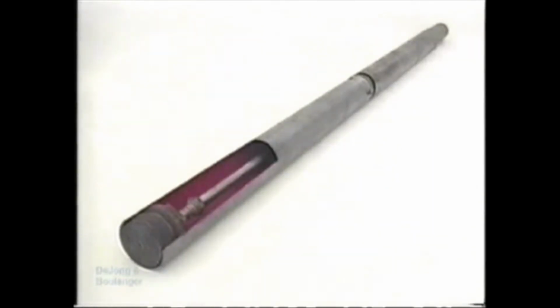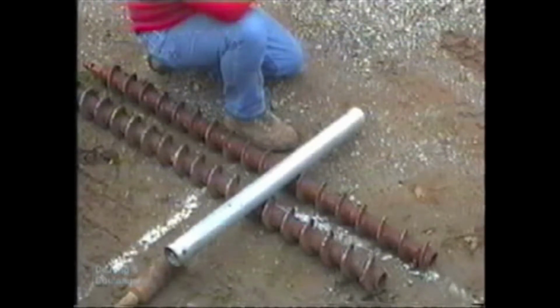Later on, downward movement of the soil sample is resisted by a vacuum that develops between the piston and the top of the sample. After the sampling tube has been advanced, the piston is fixed in its new position with respect to the tube. Both elements are rotated to separate the sample from the underlying soil, and the piston and tube are removed from the hole. Piston samplers with small area ratios are capable of furnishing excellent samples of cohesive soils, even if very soft and sensitive. The necessity for a separate piston rod rising through the drill rods to the ground surface can be eliminated by using a hydraulically operated mechanism such as the Osterberg piston sampler.